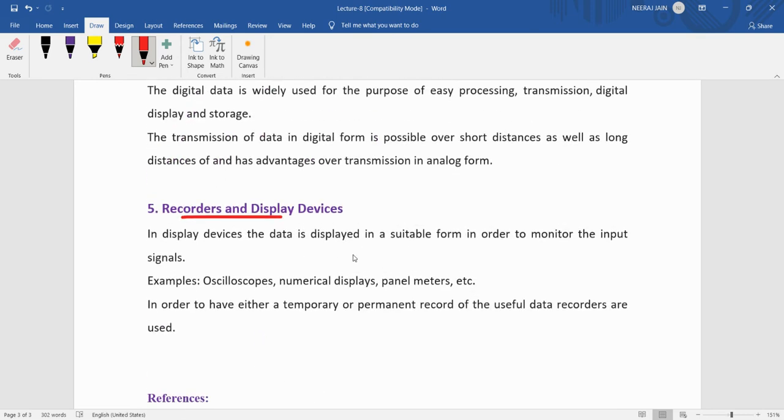Generally chart type recorders are used which record the signal, and if any fault occurs in the machine, suppose we are using a circular chart for recording, the chart will rotate with the help of a motor, and a pen also moves. Suppose a pressure signal is coming like that, and there is any dip in the pressure due to which a fault occurs in the machine, then we can see the recorder. By looking at the recorder, we can find out why our machine tripped.